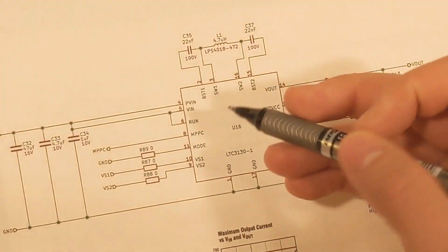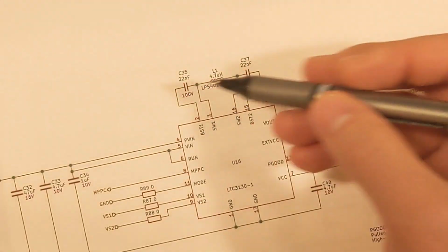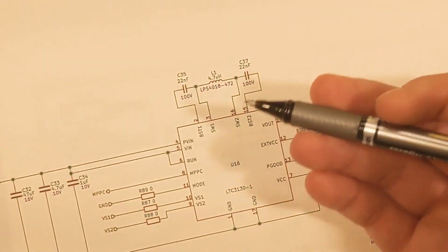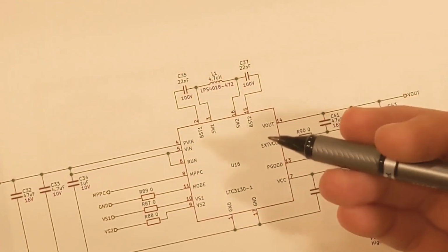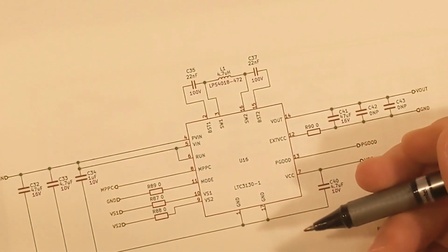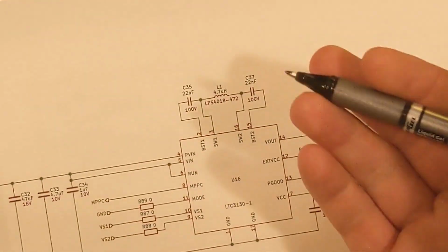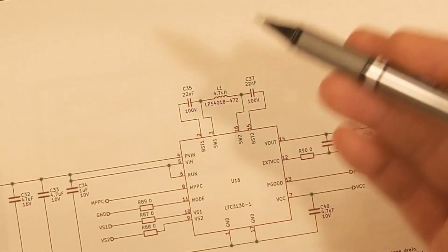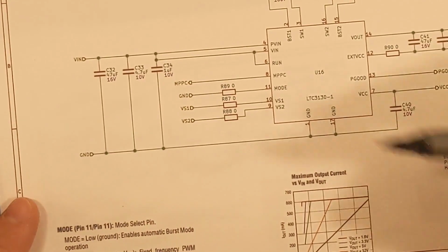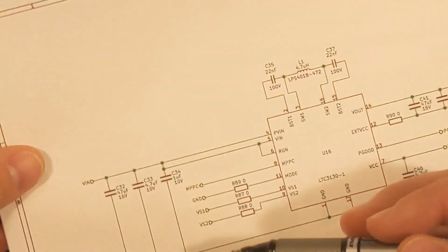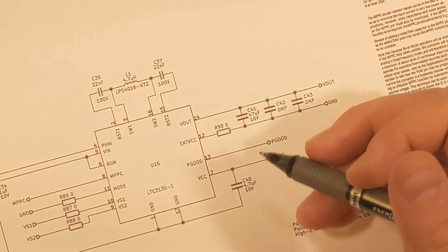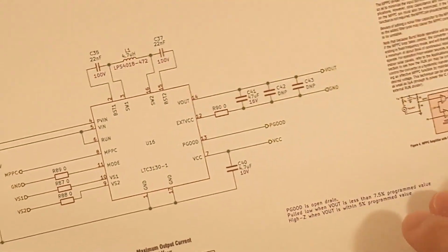Taking a look at the chip, it is a buck boost converter and has this capacitor inductor setup here. I tried to find a general value that would work for both the 3.3 volt and 5 volt output modes. So I think what I found is a pretty decent compromise for both of those, and really it seems like it would work over the whole range anyway. It's not much of a compromise. I did try to take care of adding a whole bunch of input and output capacitance, simply to eliminate as much noise as I possibly could.